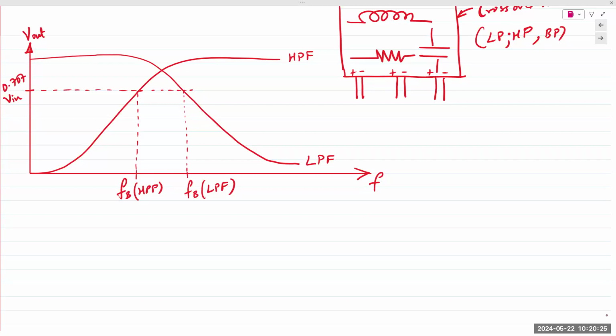So a band pass filter is a combination of two different filtering quantities, high pass as well as low pass. Each one of those filter circuits will have a break frequency or a cutoff frequency. If you have high pass cutoff frequency first and a low pass afterwards, then there's a band of frequencies in the middle that are allowed to pass through.